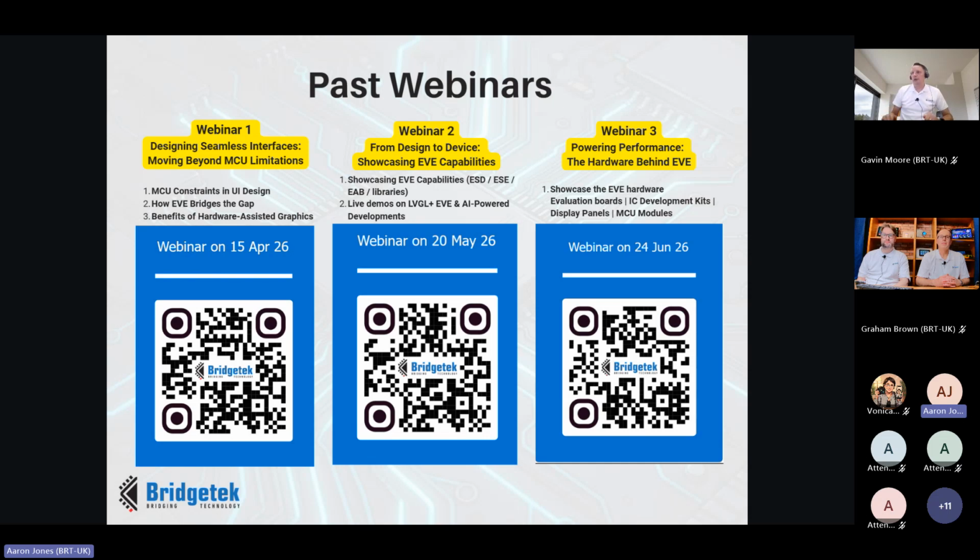Okay, another question. You showed a demo of a patient monitor. How do we draw the charts that are used in this application? Oh yeah, I think that's our MedInfo demo, which is available from our GitHub page under the Eve MCU Dev Library. So when you're using the BT820, we have a range of extensions available which you can load, and they provide additional functions such as graph drawing and other useful features like a 7-segment font display that you can use.